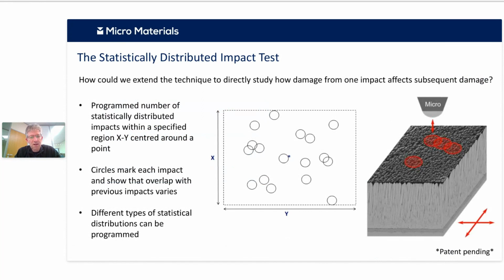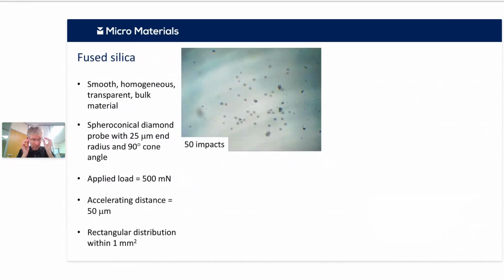So on the right is an example with a spheroconical probe, and this is a thermal barrier coating system, and this would be moving around in between the tests. That's exactly the sort of thing we've done. Okay, so thermal barrier coating systems are inherently extremely complicated, and they're very rough. So they have a remarkably rough surface by